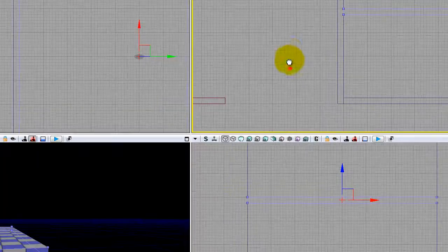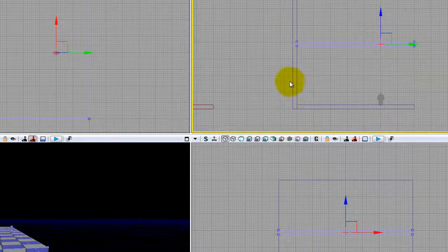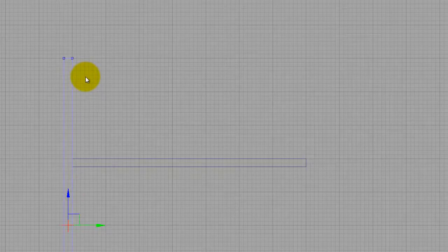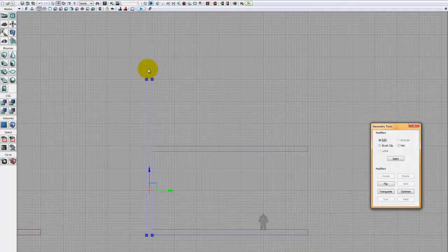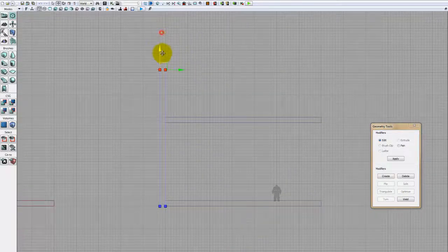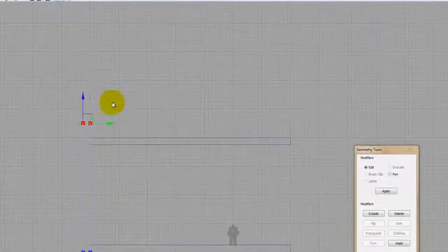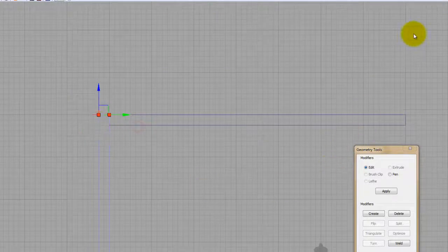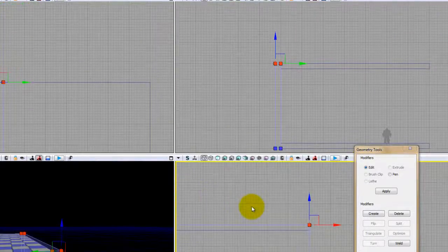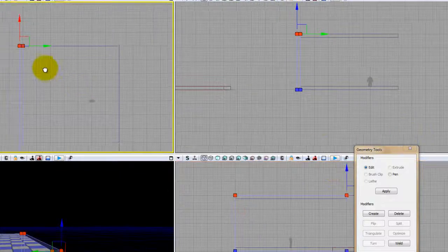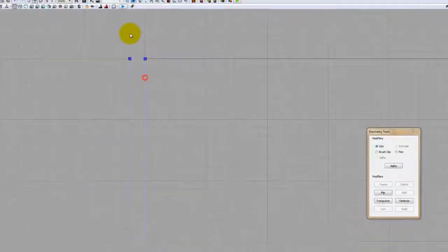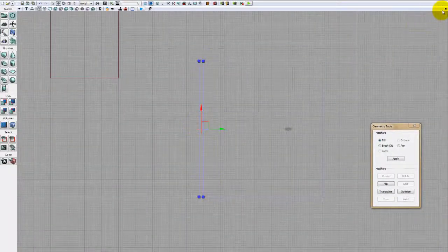So now coming back into a side view here, we'll notice this piece is really too tall, so I'm going to hit Shift 2, come back into geometry mode here, hold down Control and Alt, drag this roof piece down, well, not roof, but wall, so it matches up with the roof here. Just like that. I'm going to switch over to the top view to make sure everything is alright. So now our wall piece lines up perfectly.